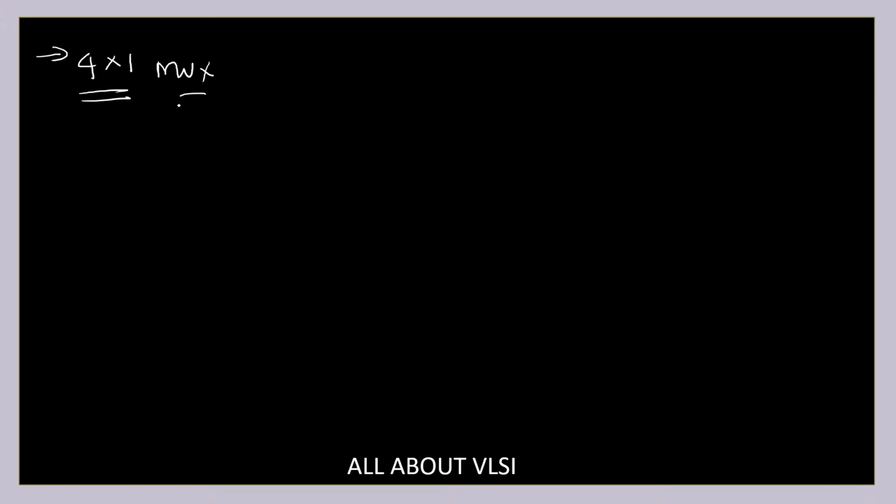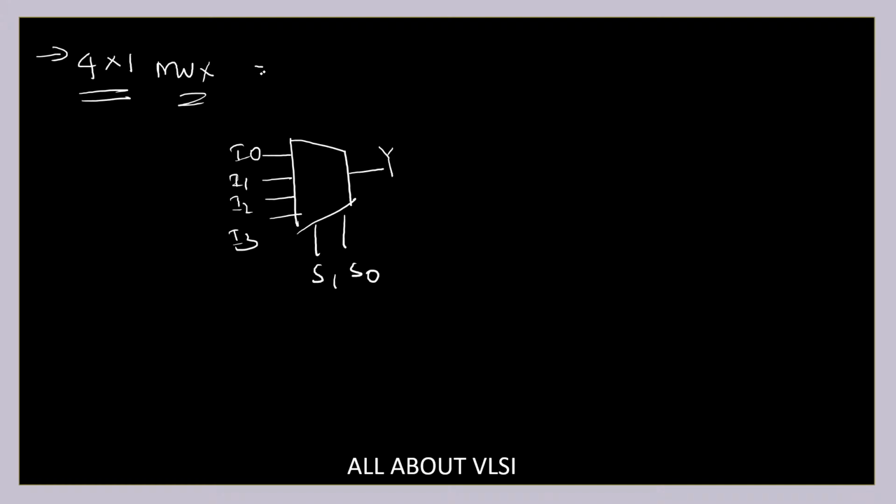Now, let's say in the case of a 4 cross 1 multiplexer, this is how it is going to look, where I'm going to have four inputs and one output. This is I0, I1, I2, and I3, and this is my output Y. Coming to a simple 4 cross 1 multiplexer, it is going to have two select lines. So it is basically 2 power 2 cross 1, and these are my select lines.